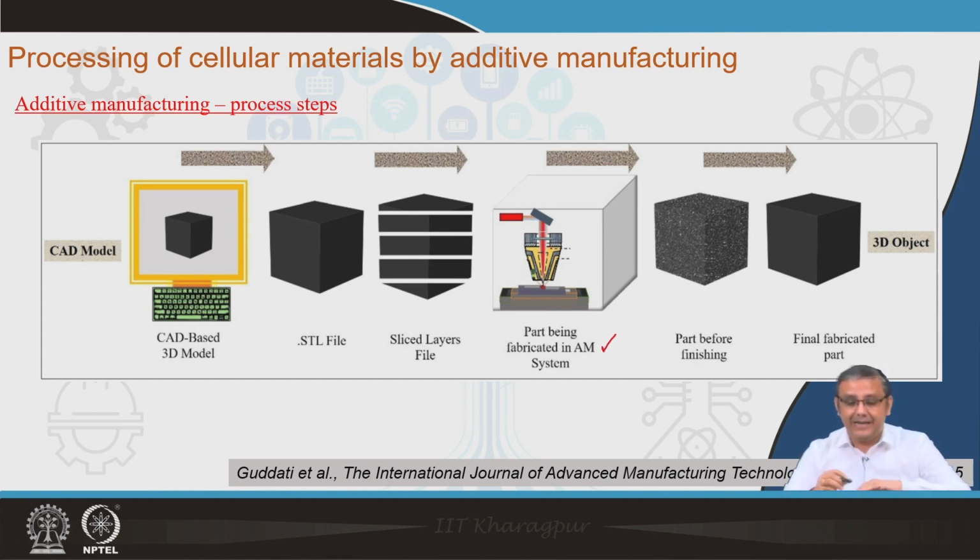and then by some technique, either laser deposition or some other technique, the material or powder, which can either be a powder bed or a powder deposition, is fed onto the platform. This deposition follows a predefined path to create the final design. Once one layer is complete, the platform moves down by a certain amount, which corresponds to the individual layer thickness, and then the same process is repeated.